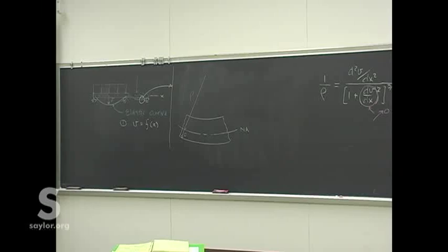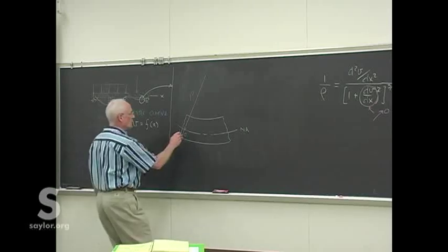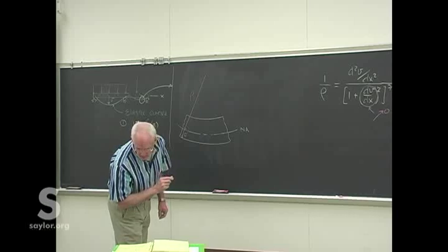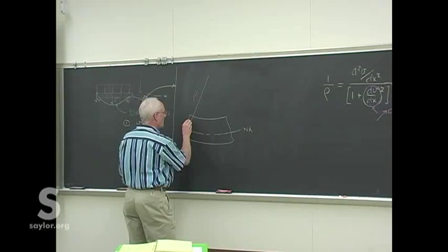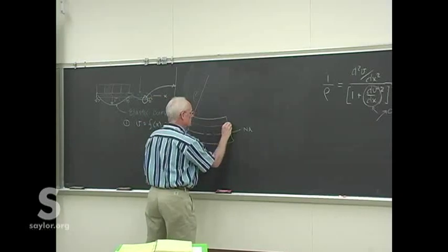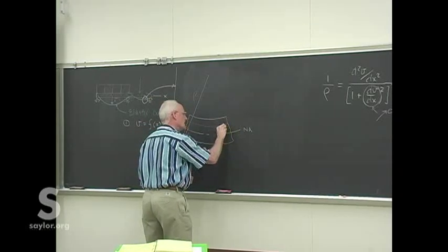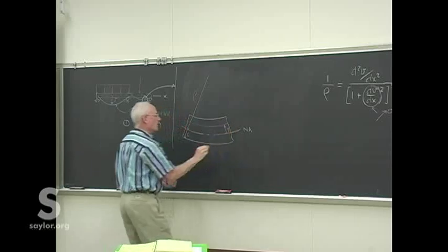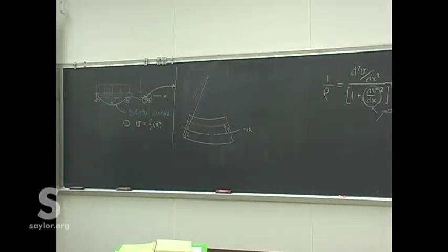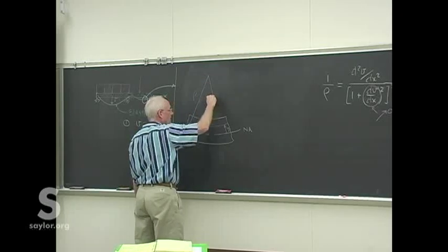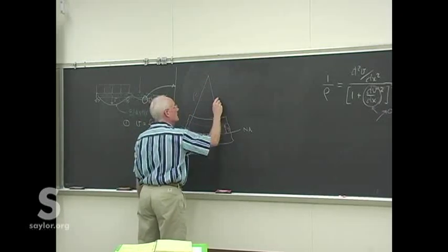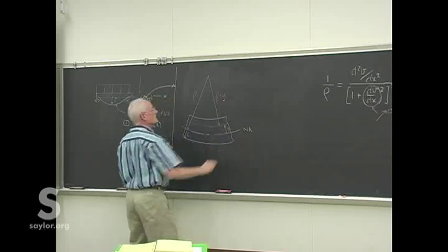don't forget that from the neutral axis to the extreme part of the beam, we always call that C. But anything else in between, we called Y. So let's just go up to some arbitrary point, Y. And in fact, for our measurements, that's actually in the negative direction. So the curvature down to that point is rho minus Y.